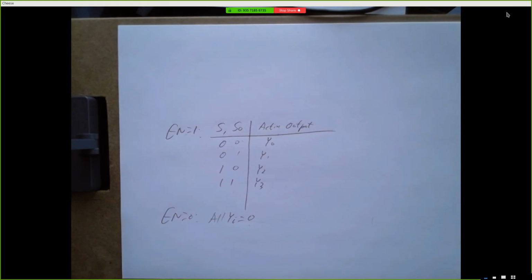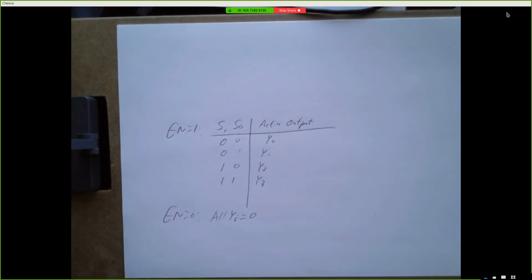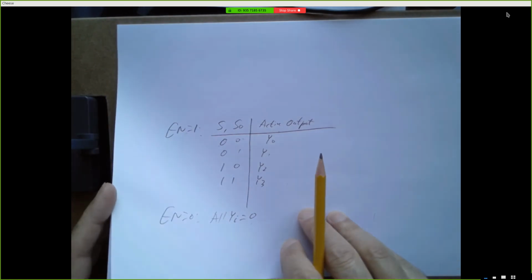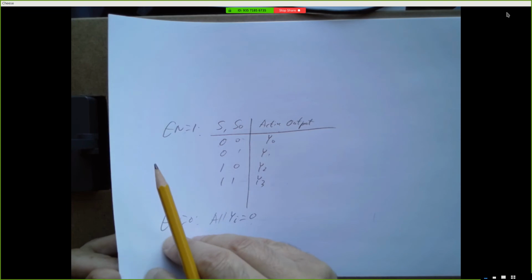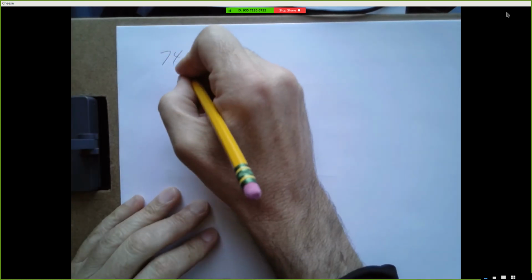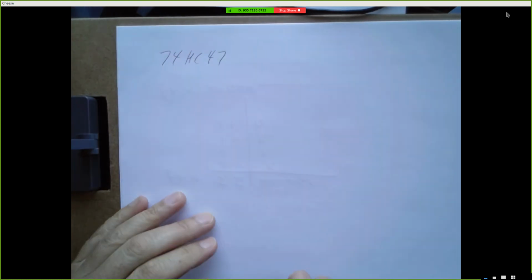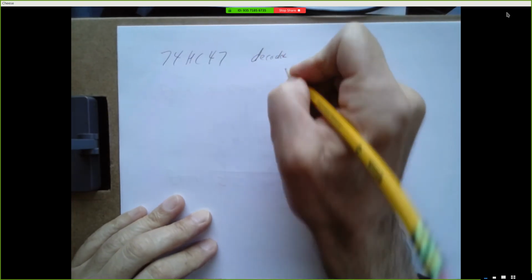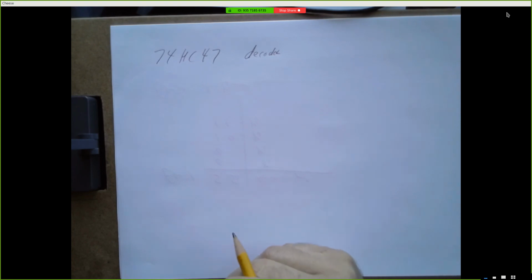All right, so those are Muxers and DeMuxers, but there's particular Muxers and DeMuxers that we find useful beyond just routing signals or compressing truth tables. One you're going to find really useful in lab 4 is a 74HC47. This is a decoder, so it kind of works like a DeMuxer. It takes a few pins and it drives more pins.